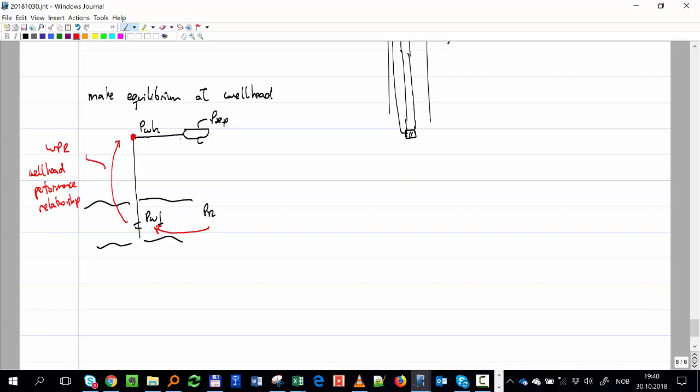And now I have to do the same from the separator to the wellhead. So how is that curve going to look like? From the separator to the wellhead, we are saying in all of our analysis that P separator is very close to P wellhead, because they are relatively close and they are the same. Thus, that curve is not a curve really, it's just a constant number. So that's the required pressure at the wellhead, just a constant number.